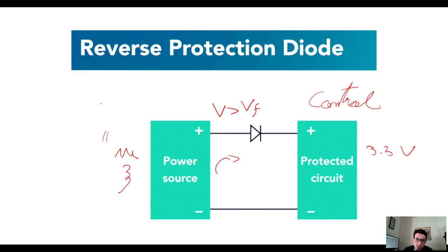this is a thing that I want to make sure I mention right now. If your battery is providing 3.3 volts from your source, so it's a 3.3 volt battery, then this is not going to be enough to operate your sensor, so you're going to have issues reading your full scale, because in order to get this voltage through, you need 0.7. So what you end up having here, by conservation of charge, is 3.3 minus 0.7, and of course this is going to be 2.6 volts.